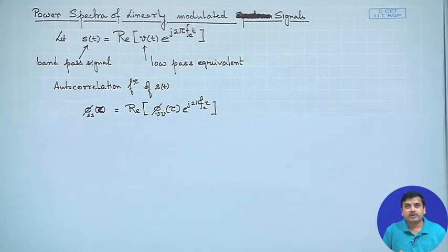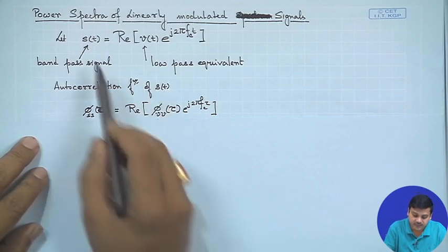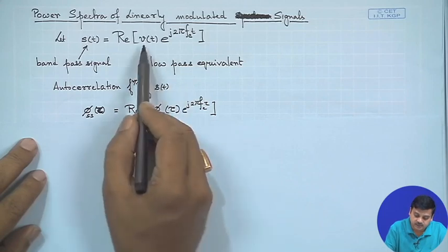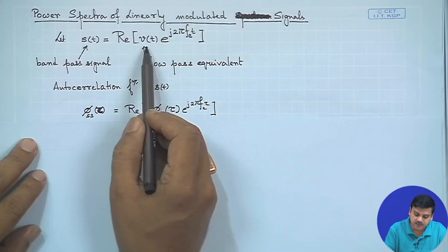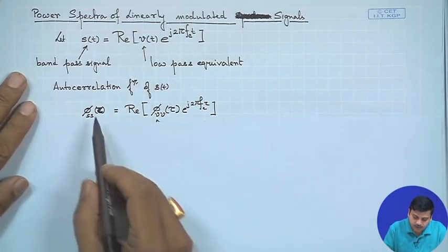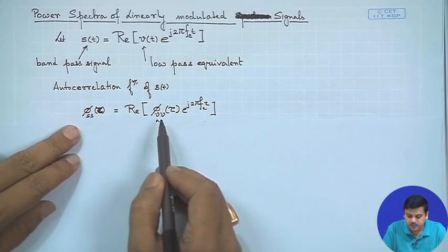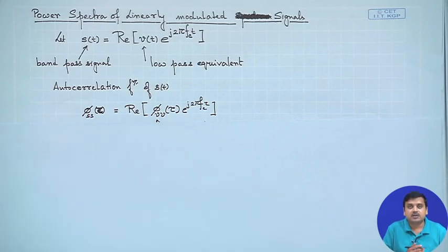So, as we said that we are interested in the autocorrelation function. So, we will take this autocorrelation function of s(t), because this is the stochastic process, that is what we have said, because v(t) is an outcome of the information sequence, and hence if this is stochastic, this also is a stochastic process. So, the relationship of the autocorrelation function of the pass band to that of the base band was also established in our discussion when we studied the narrow band stochastic process.